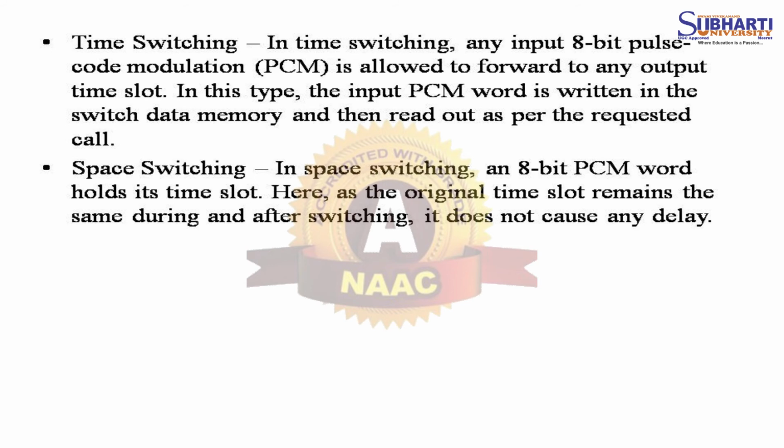In space switching, an 8-bit PCM word holds its time slot, as the original time slot remains the same during and after switching. It does not cause any delay. Digital space switching. A switch transfers signal from one input port to an appropriate output. A basic problem is then how to transfer traffic to a correct output port.